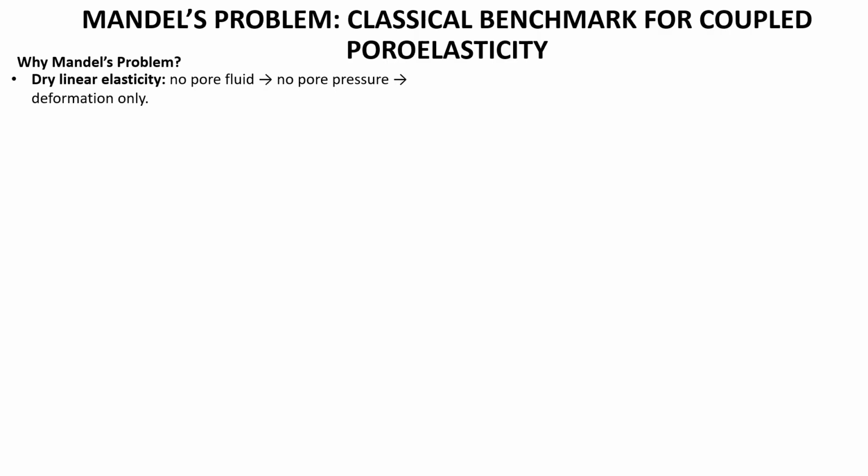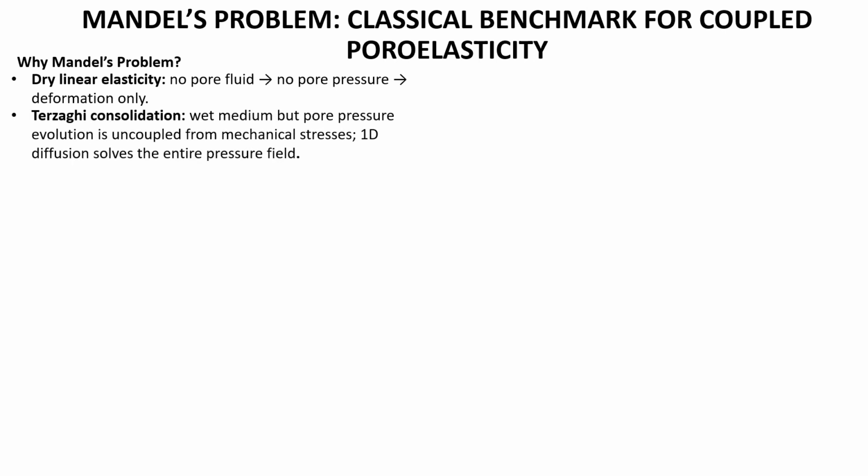Other classical models do not capture this coupling, such as the dry linear elasticity, where there is no pore fluid, so deformation is purely mechanical. Also, in the Terzaghi consolidation, pore pressure evolves by diffusion, but mechanical stresses do not feed back into the pressure field. So neither of these physics do we need.